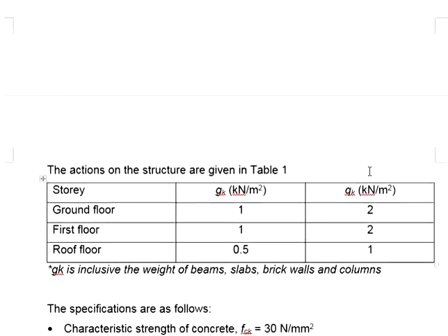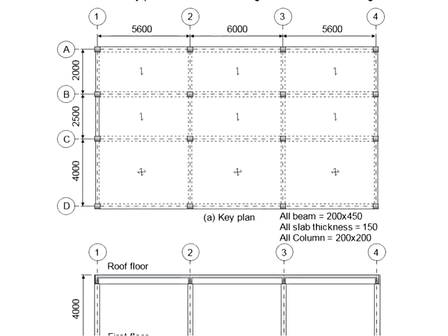And if you see the design of the column, which is a square section, the effective depth of the reinforcement bar due to the bending of the column will be relatively low as compared to the beam. But if you see the area here, the cross-section area seems to be rather big.